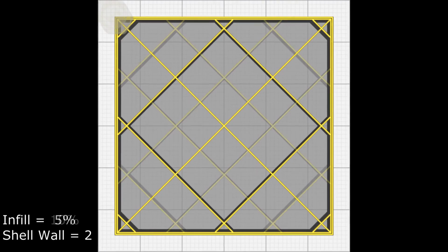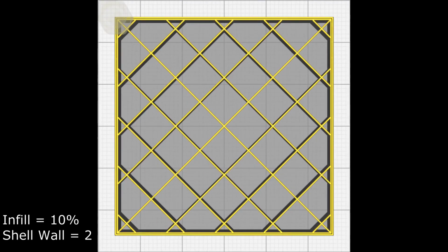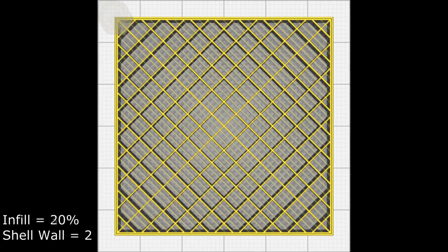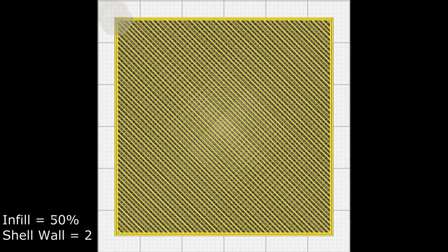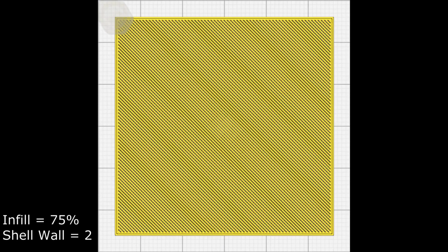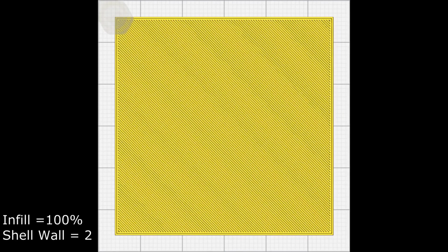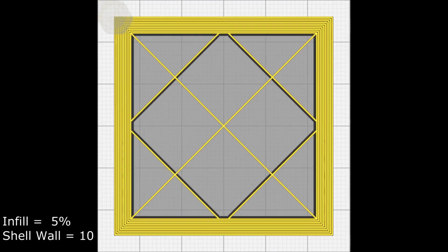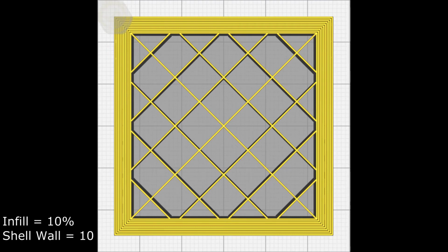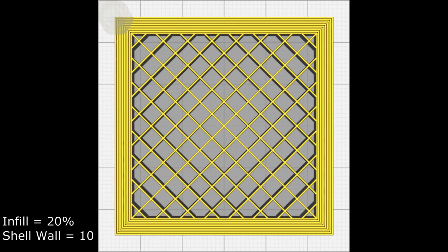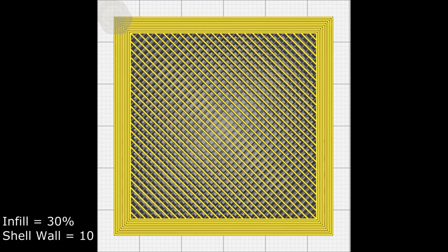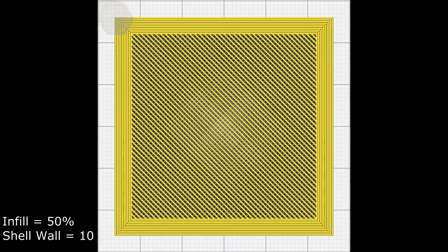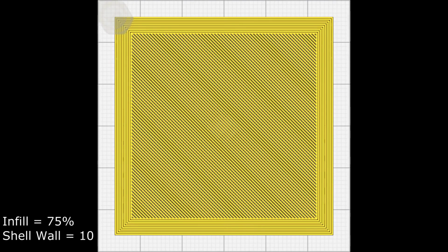Remember, strength based on infill alone will plateau around 75% infill and up. You won't see much change in strength in a part with a 75% infill other than it costs more to print. To get the best of both worlds, that being a strong part while using the least amount of material, you'll have to experiment with increasing the thickness of your part's shell along with infill. There's a magic ratio between both that will give you economical strength, assuming your part is sufficiently designed in the first place. Yet another option is adjusting the wall shell count, and that can also help you discover that magic ratio to strength and part density. So part density now being the infill along with the shell count.